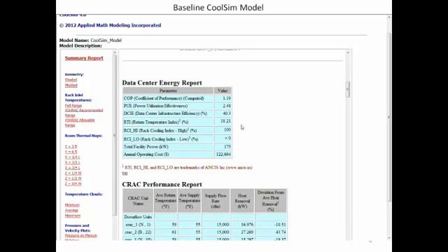Now here, Magnus, the RTI on this particular report right now is showing 18%. The first thing to understand is what is the return temperature index, RTI? Well, it's really the ratio between the volume of air going through the electronic equipment compared to the volume going through the air handler unit. So first thing we can notice is that when the RTI is 100%, we have a balance, so we have as much airflow coming out from the crack units as we have going through the electronic equipment. You might consider that to be like a target number.